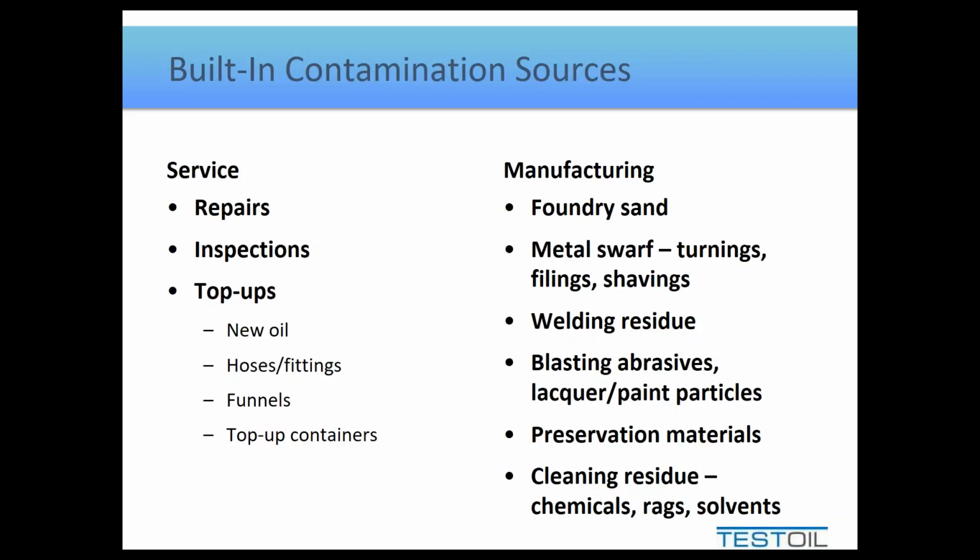Second last on the list is preservation materials. I'm not actually referring to anything solid there. I'm referring to preservation oil. There's been many of our customers who have had issues over the years with a brand new piece of equipment that's not been properly flushed. Once it's filled with the final lube, there tends to be some issues, and nothing seems to be wrong with the lube, but there does seem to be a reaction going on.